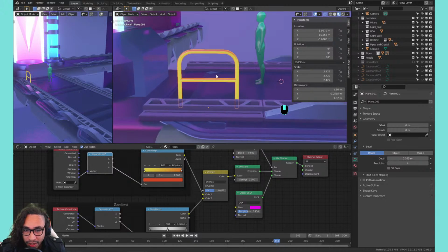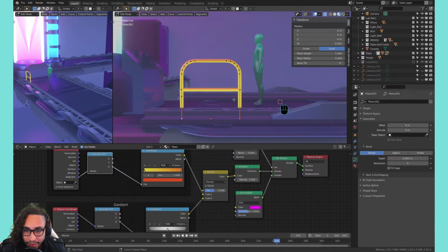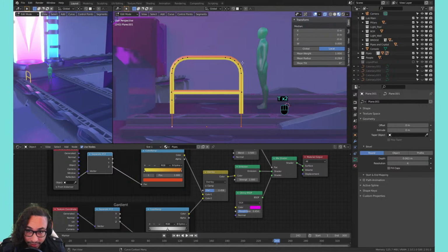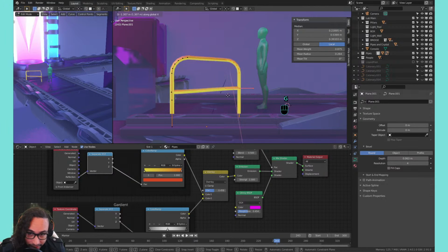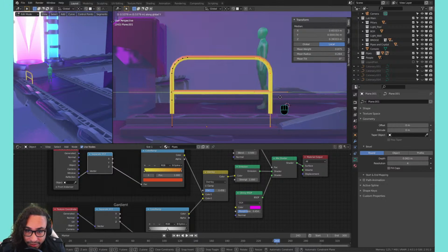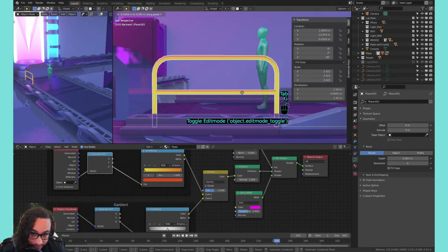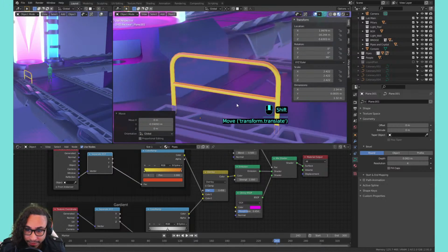All right, and then I think these segments for the rails, I want them to be a little bigger. So I'm gonna go to edit mode. I'm gonna do box select here. I'm going to select this half at the end. And if I grab it, I can grab it around, hit X, not X, Y. And I'll make this railing, I don't know, once again, I'm just eyeballing it. There. So our railing is looking all right. So our railing can move up to here. And this is just temporary stuff, you know.